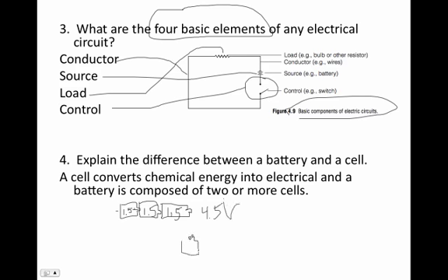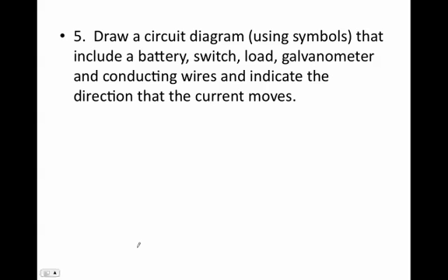However, you could hook them up differently. You could hook them up like this, side by side, and then hook wires to them. And so if we do it this way, and they're each 1.5 volts, we hook them up in parallel, and so the total voltage here, even though they're all in line, is 1.5. But what happens is, even though it's less voltage, if this one drains, then we still have 2 more, so this situation in parallel will last longer.